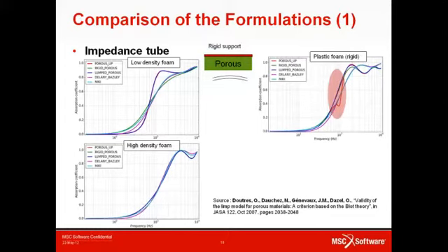For the high density foam, all the formulations match pretty well with the reference Porous UP model. For the low density foam, the lumped model fits much better than the other models. And for the plastic foam, none of the equivalent fluid models is able to capture the skeletal resonance occurring around 1 kHz.